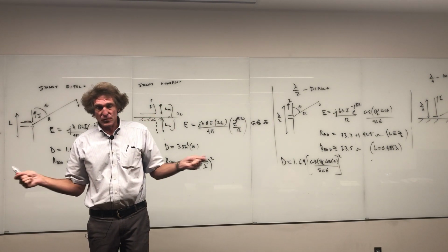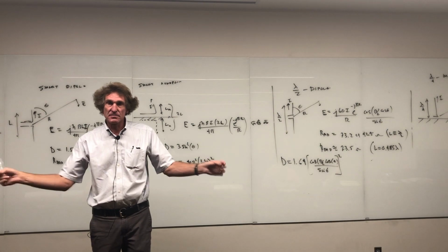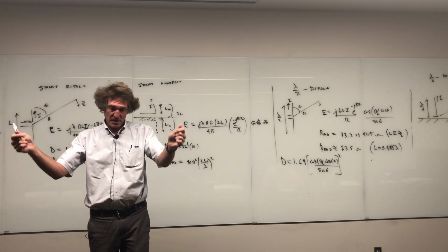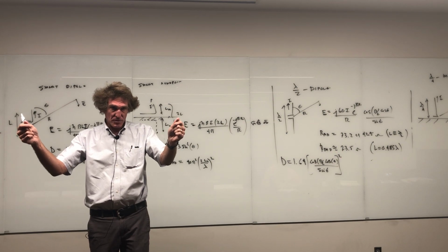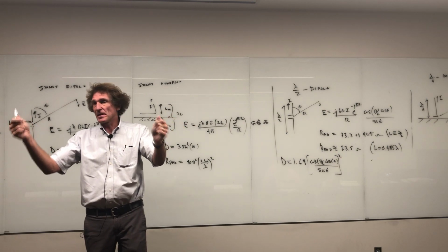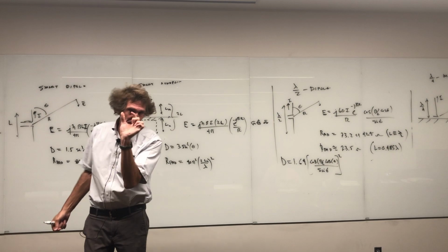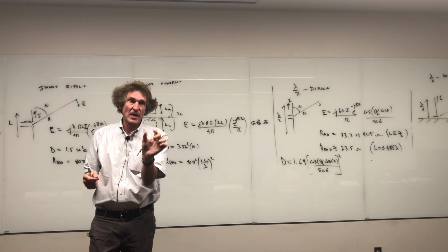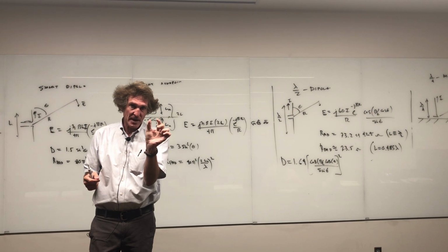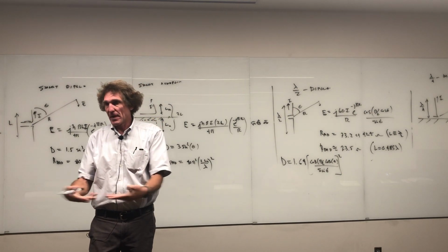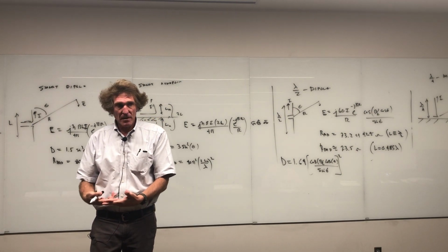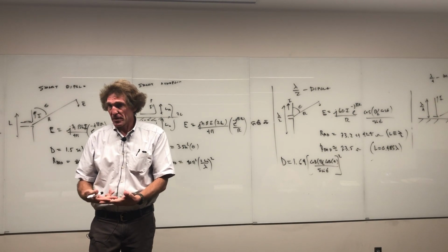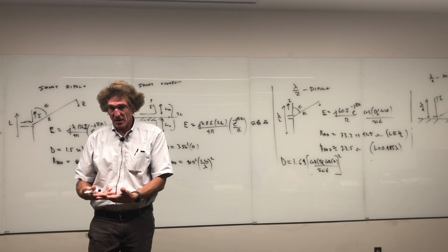One thing is, if it's real arid, they get cross-hatched mesh, like the metal netting you see put down when they pour cement. But they'll make sure that the length between the square pieces is 1/10 of a wavelength or less. It has to be that or it won't look metal. Then they'll bury that a couple inches below ground, and that will effectively emulate a pretty good ground connection at the frequency you're talking about.